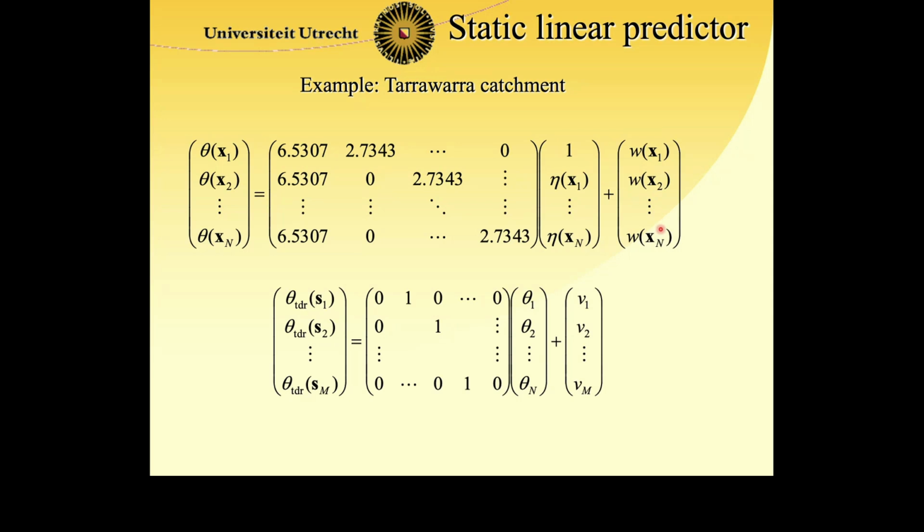So if we have the variance and we have the range, and we know it's a spherical semi-variogram, we can calculate the semi-variance between any of those, and the variance minus the semi-variance is the covariance. So we can completely fill the covariance matrix Q. So I've done that, and then let's see what happens.